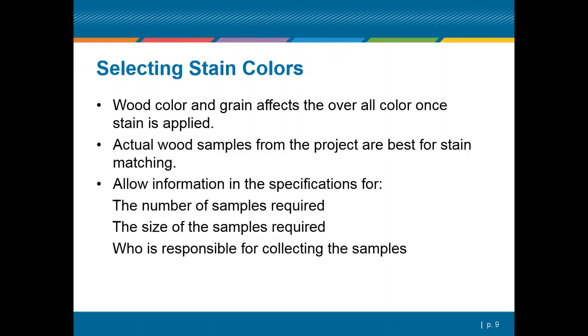If we can have the actual wood that's being used, we can be more accurate, and that's something you may need to add into the specification, especially if you're going to have some wood finishes that are integral to the project. So understanding the number of samples required and the size of those samples, whether you want a 4-inch by 4-inch sample or an 8-inch by 8-inch sample, whatever size it happens to be, would be good information to include in the specification so that